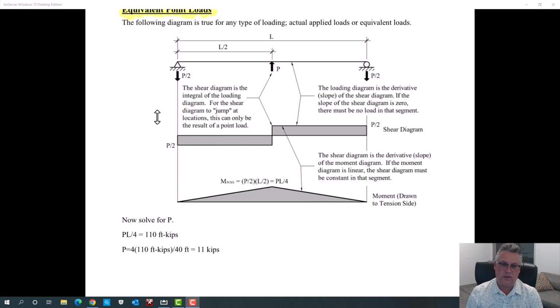That's what we do as engineers. If somehow, some way, the pre-stressing can be depicted in our calculations as just another load, that's a game changer for us. Now it's just another load case. Now the dead load is the dead load case, the live load's the live load case, and the pre-stressing can be another load case. And we just mix and match and combine, load factor, do whatever it is that we need to do to design whatever it is we need to design. But the fact that the pre-stressing becomes another load case changed the world. And I don't think I'm being over dramatic. It certainly changed the pre-stressed concrete world.